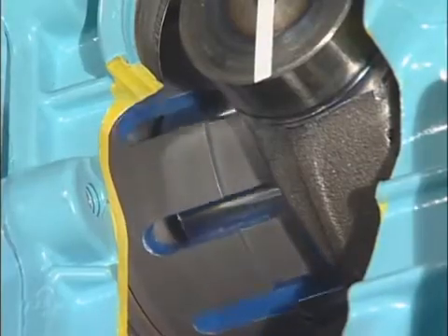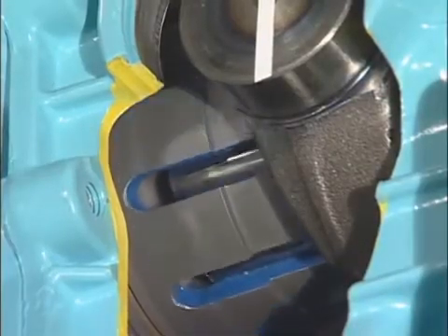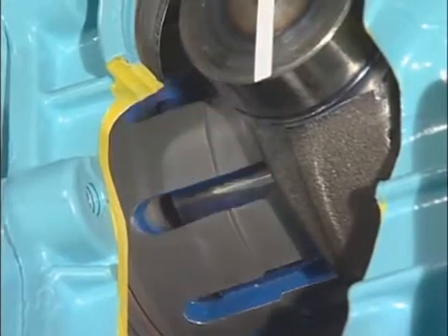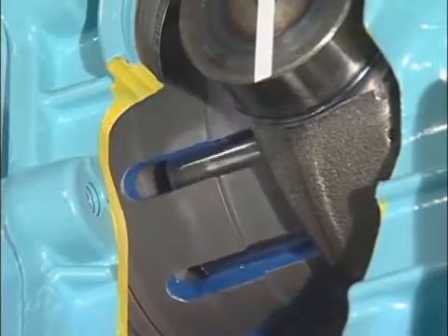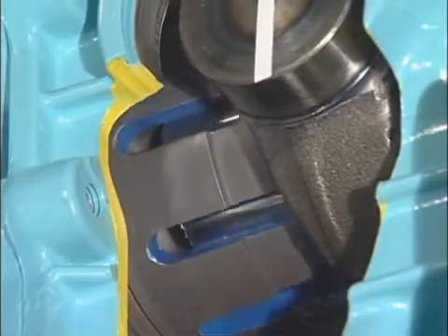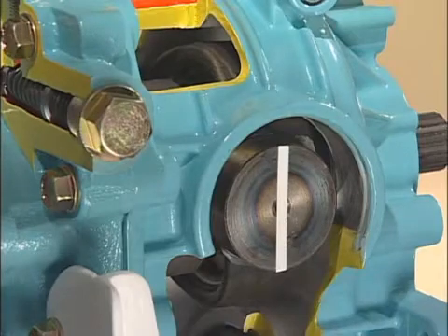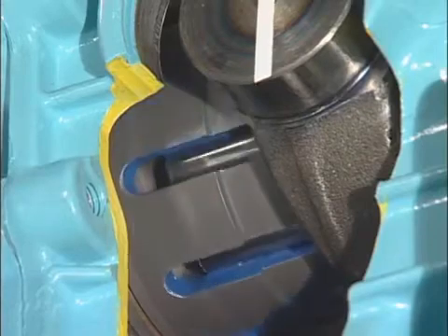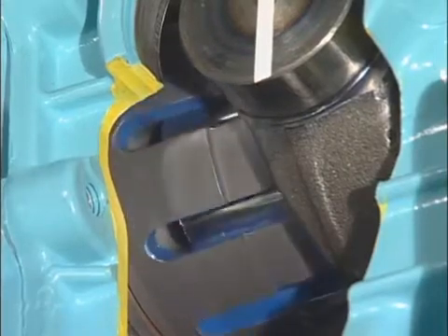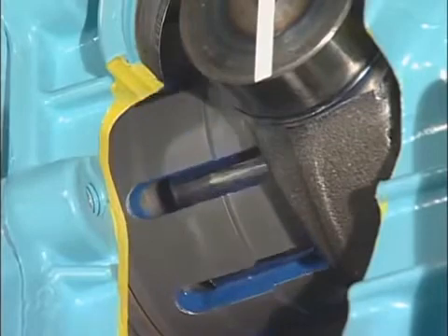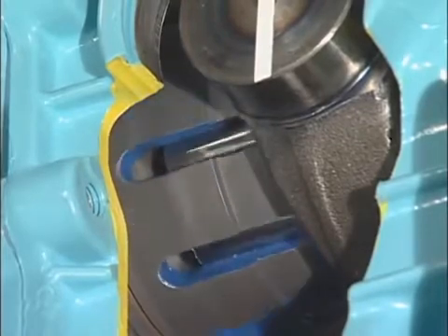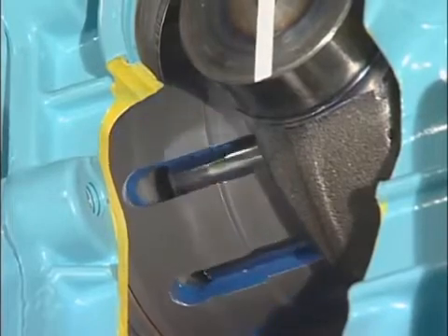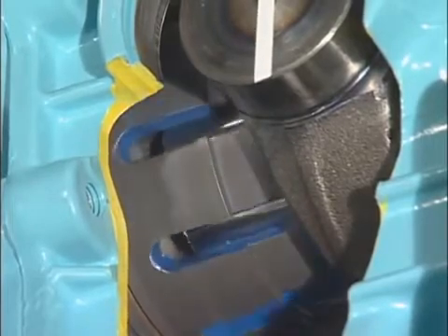The pump always rotates in only one direction, as it is directly driven by the engine. Please remember that the cylinder block and pistons are always filled with hydraulic oil. Here, the variable swash plate is in a vertical position. Now please pay attention to the cutaway part of the cylinder block and watch the movement of the pistons. As you can see, all the pistons remain in the same position, with the result that there is no pumping action.